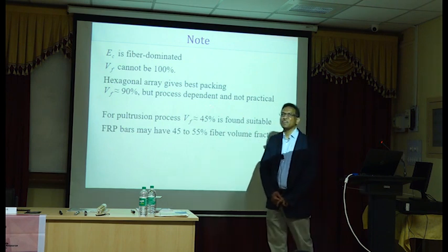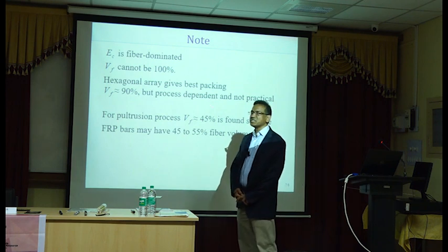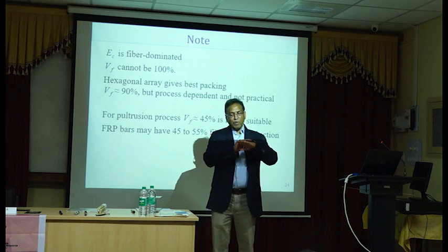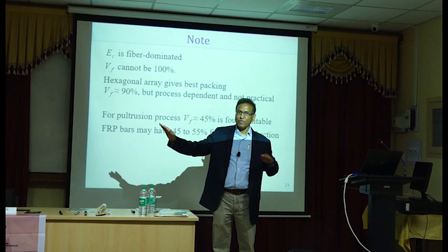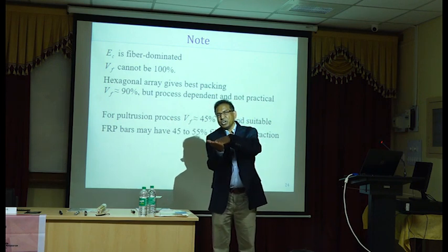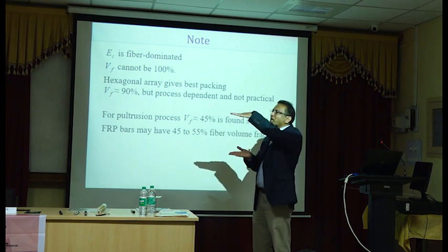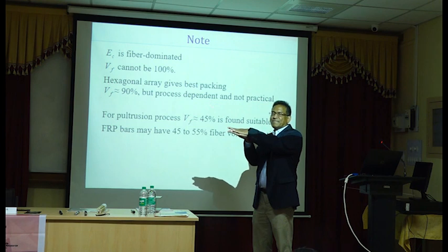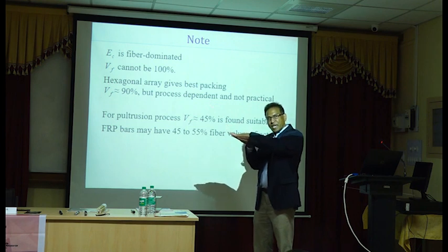Very good. That's a very good concept to remember, because in most of our structures, the alignment of the fibers will be in the direction of the stress. That's given. But sometimes you may have interlaminar shear. That means one layer of your composite may want to slide relative to the other layer.